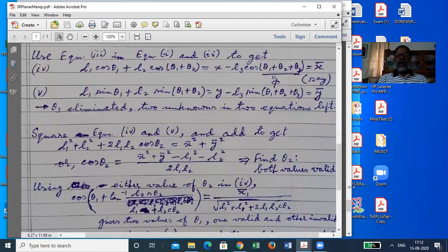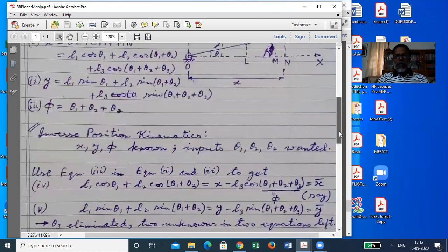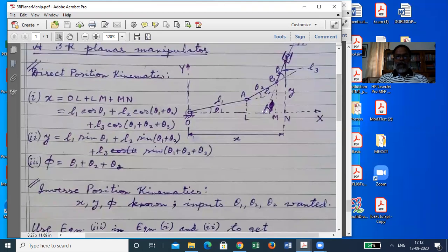Can you see how they would look? This theta 2 is something like 19 degree or 18 degree, something like that. For the same position of B, A could have been up, okay? In which case it would look like this and this. And in that case, theta 2 would be clockwise, negative.